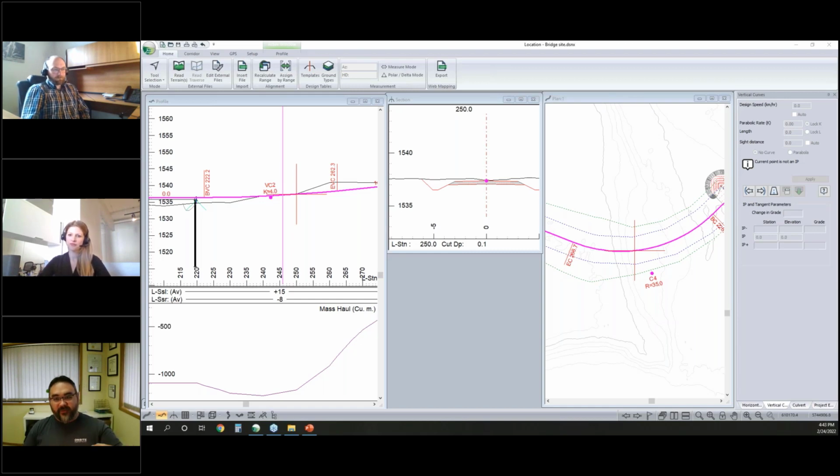Because as soon as you're overlanding, if that peat is really weak, you're adding the cost of the geosynthetic, geogrid, or whatever material you're putting underneath. And you also may have to have a bit better quality material because it has to be stable on top and spread load on that weak layer. So that's a tough question to answer because there's so many things that are going to affect it.